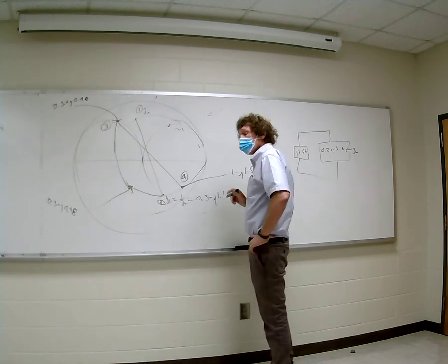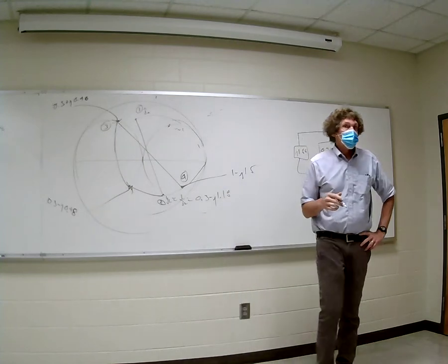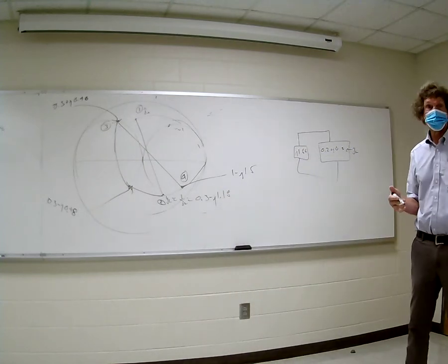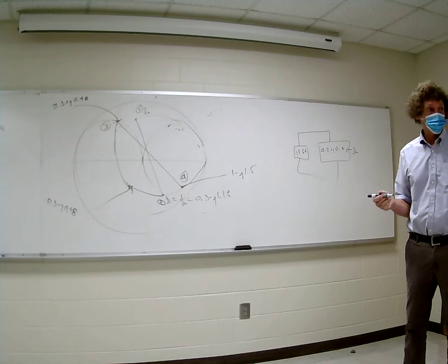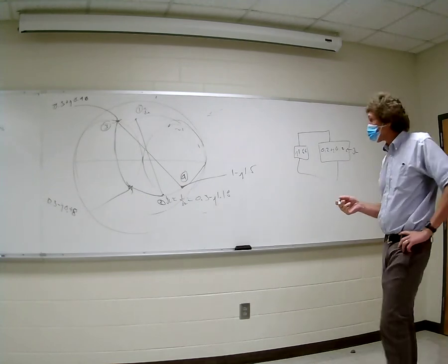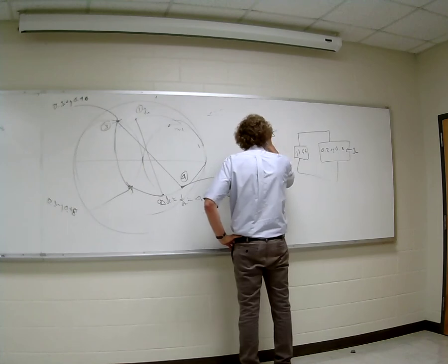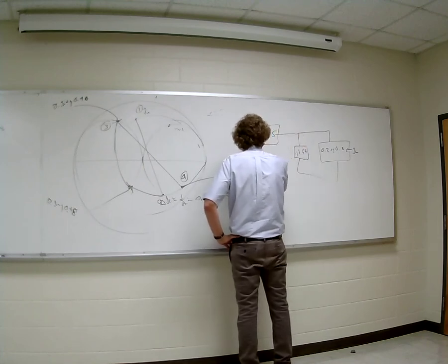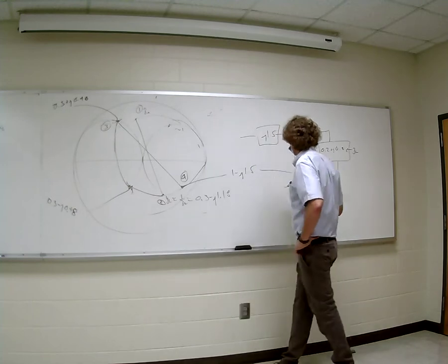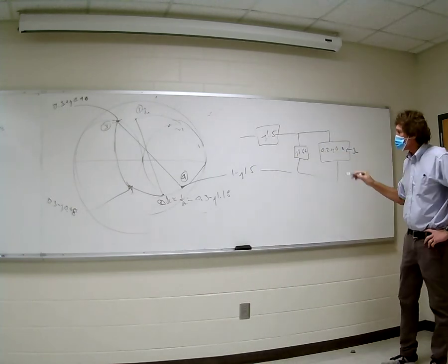Okay, that's right. Now, I need to add in series an impedance of plus j1.5. Agreed? That would be an inductor. I'm just going to put it in. j1.5. Notice they're both positive. That's an impedance normalized. That's an admittance normalized.